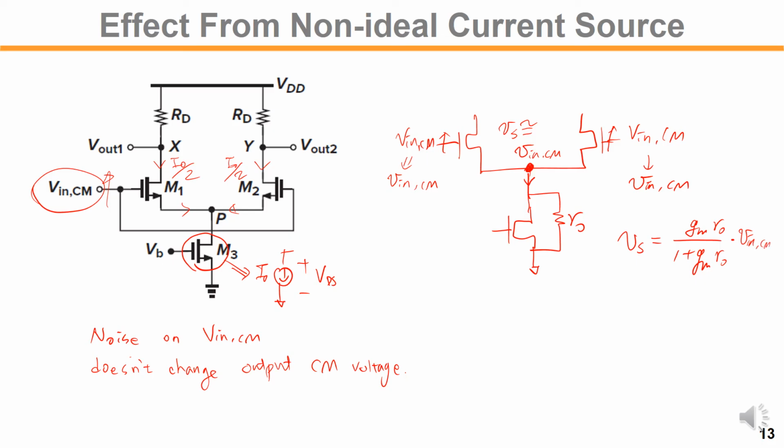So this gm is, let's say, big gm, because each differential pair gm is gm and gm, then overall we have double the gm here, so 2 times gm. Okay, so we have a similar voltage variation on the source node that will create what, the current variation through RO.